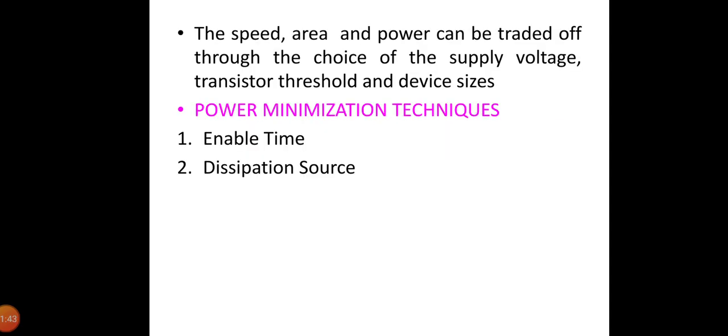The first category is enable time. Some design techniques are implemented or enabled at design time. Transistor width and length, for instance, are fixed at the time of design. Supply voltage and transistor threshold, on the other hand, can be set either statically during the design phase or changed dynamically at runtime. Other techniques primarily address the time that a function or module in a digital design is in idle mode. It is only logical to require that the power dissipation of a module in sleep mode should be absolutely minimum.